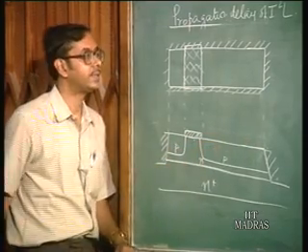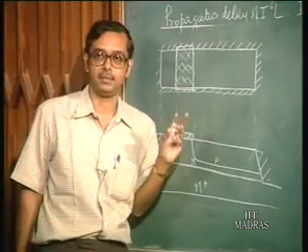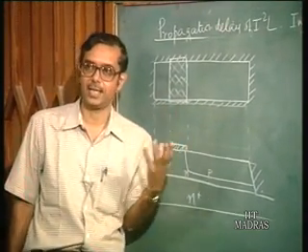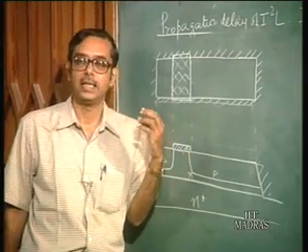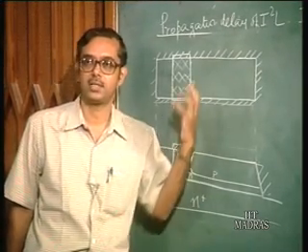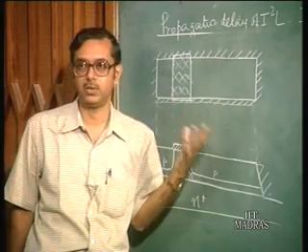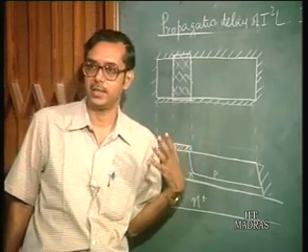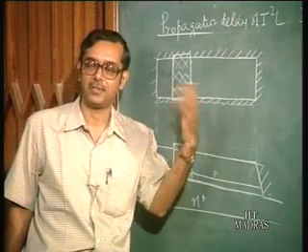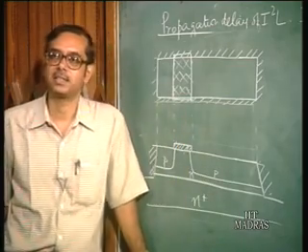For that, a technique which is used is polysilicon, which is polycrystalline silicon. This material is very interesting in the sense that it can be deposited on silicon at relatively low temperatures. Relatively low means around 600 degrees centigrade, whereas most other processes usually take place at 1000 degrees, so even 600 degrees is considered low.